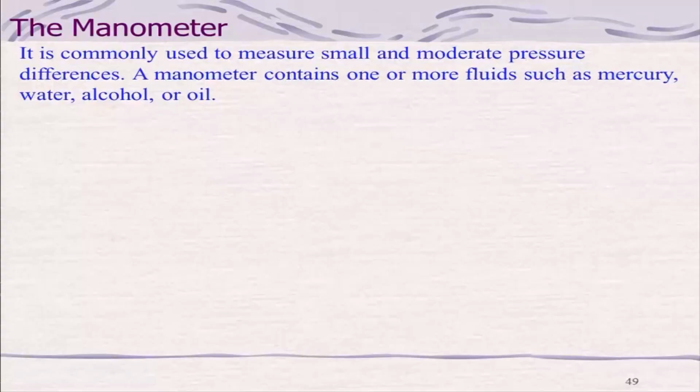And some of the manometric fluids are basically water, alcohol, oil kind of things, right. And we can also devise some of these which will be helpful depending on the situations. For example, the question is where you will use mercury, where you will use water, where you will use alcohol, and that will depend on the properties of these fluids, particularly the density.